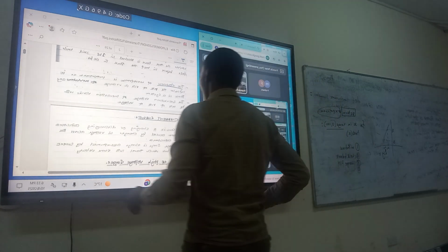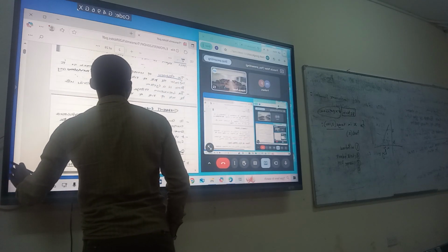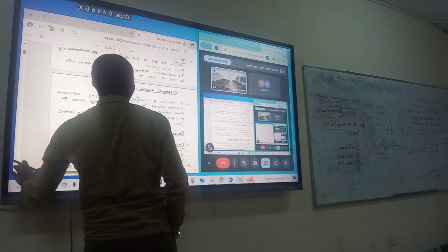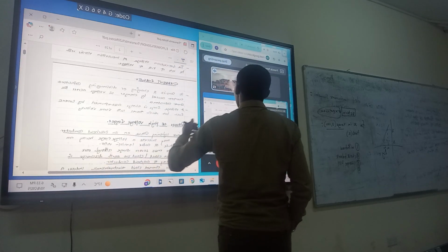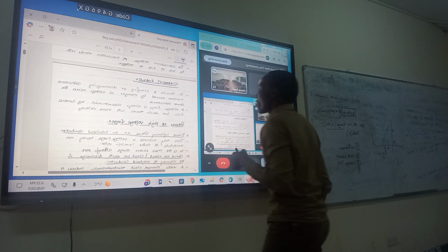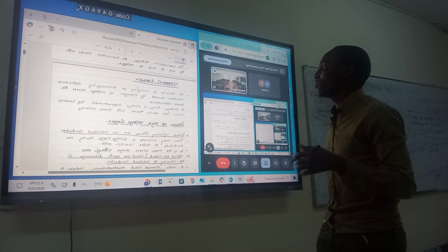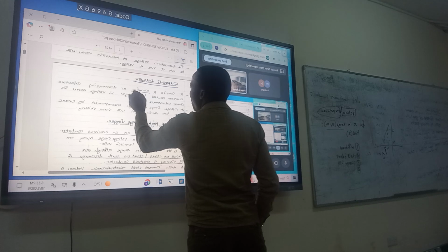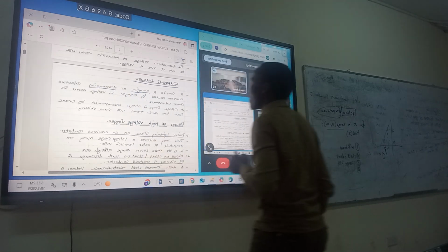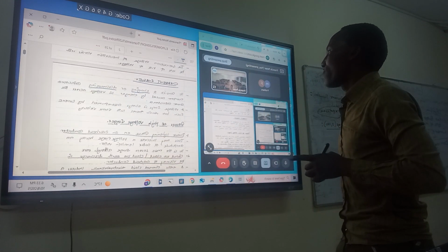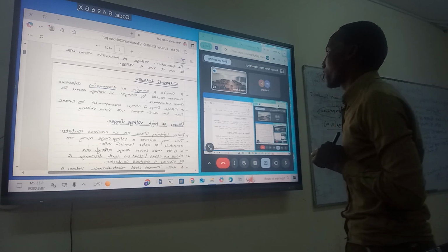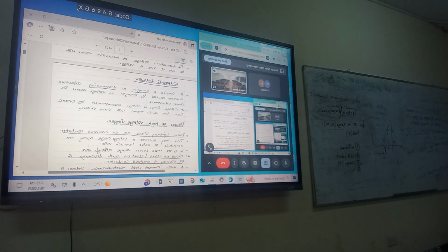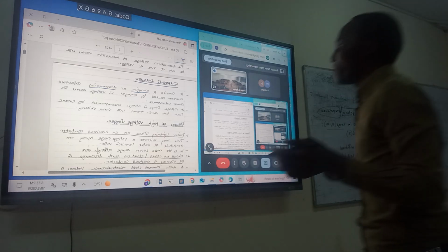And therefore, we want to check the current surge. That was for the voltage surge. The current change consists of charging or discharging capacitance current that is caused by a change in voltage across the shunt capacitance. And therefore, a voltage surge is always accompanied by a current surge, which travels at the same velocity.